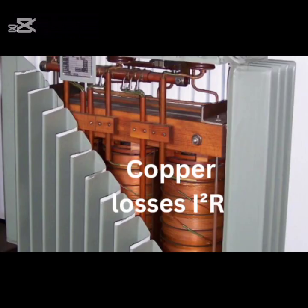1. Increased losses in the power system. Low power factor leads to higher currents for the same amount of real power delivered. This can increase resistive losses, I²R losses, in electrical conductors and transformers, leading to wasted energy and higher operational costs.